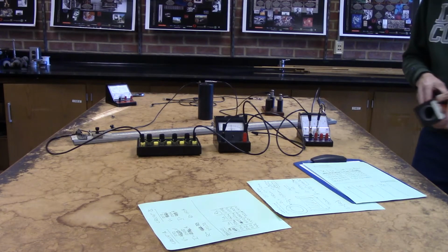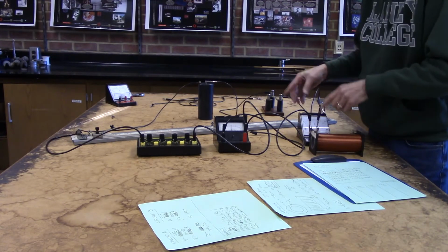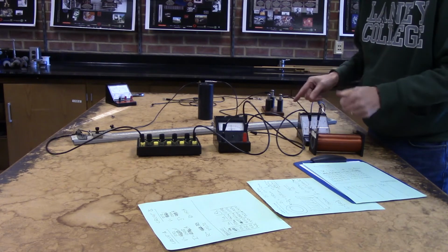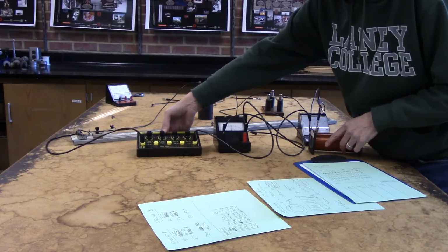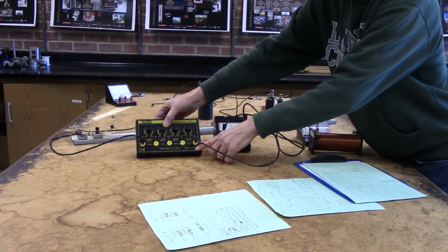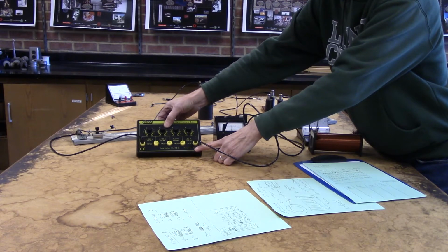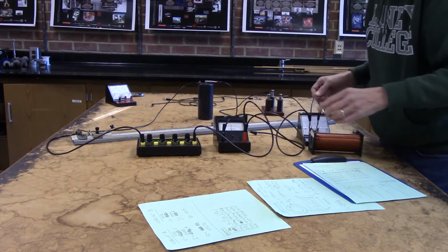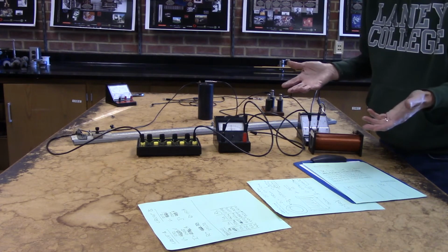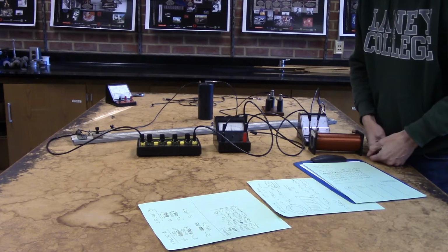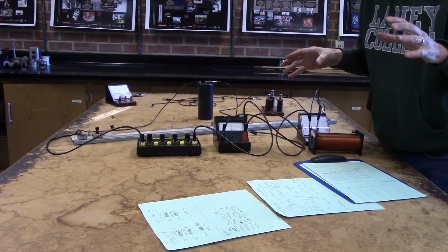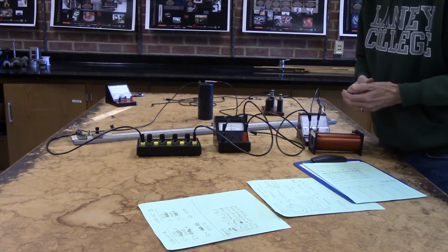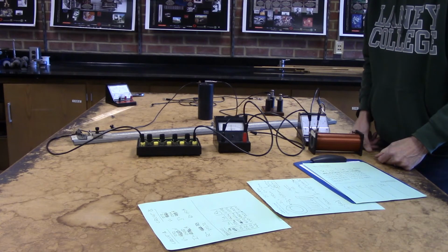I'm feeling more confident using this circuit now that I've measured 2 different devices. Now, unfortunately, this resistor box only goes down to individual ohms. This can only be set as low as 1 ohm. And to measure the ammeter, my guess is that the ammeter will have lower resistance than 1 ohm. So I'm going to have to go pull out some other resistor boxes that go even lower. I guess I could try it with 1 amp.